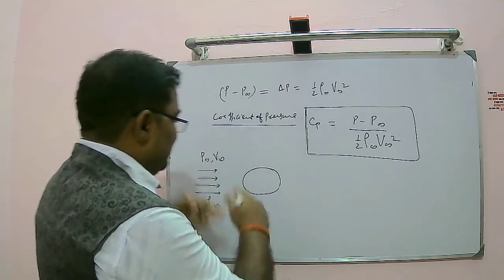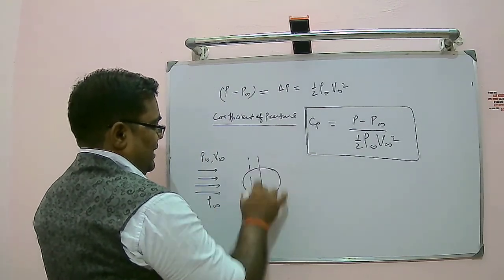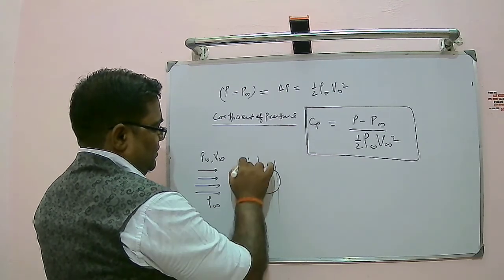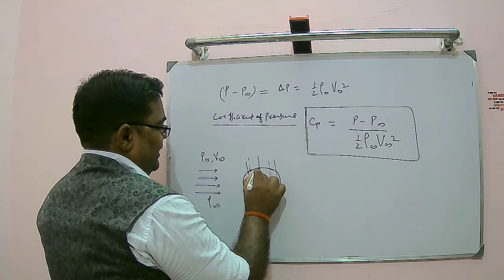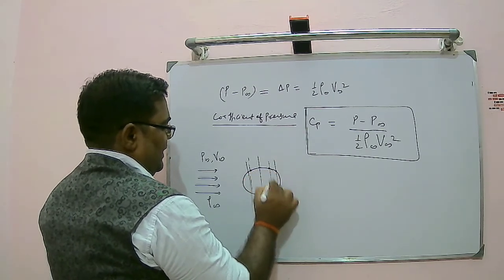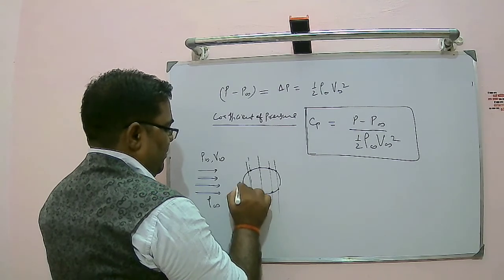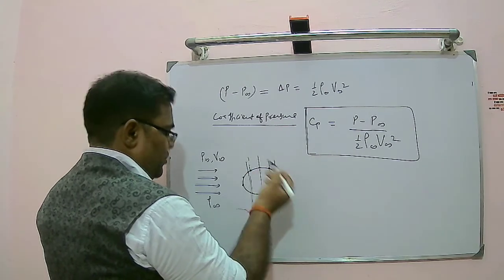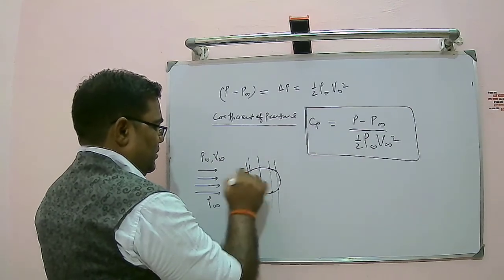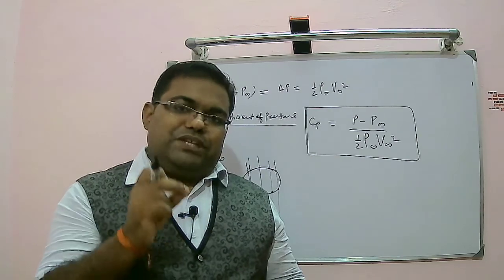We will divide this surface into n number of points. So if we divide like this, like this, like this, for the sake of it I am dividing it, we'll get these kinds of points over the entire surface, bottom and top. At the same symmetrical location you will have a point. One point you can put here, one point you can put here, or in between also you can put some points, right? So at all these points you will put the static pressure ports.